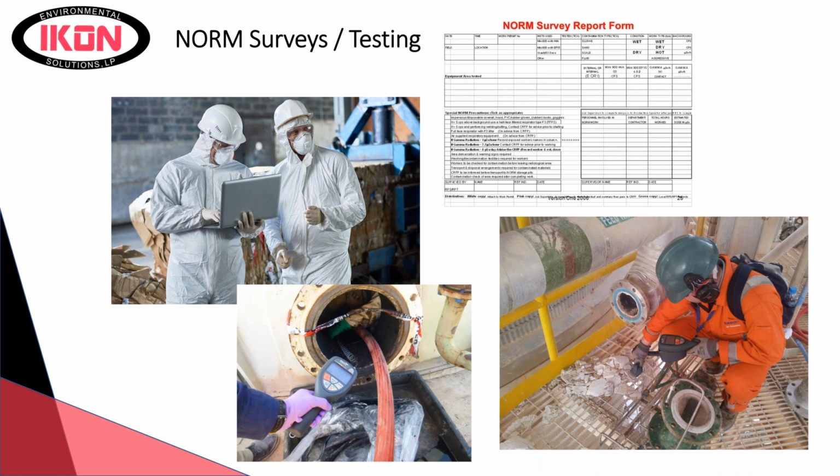Or, like I said, if it's a pile of pipeline rouge or a pigging line on a propane feed or some Y-grade field gas that pushed out a 6-inch Tootsie Roll looking thing of sludge, you're going to use the gamma scintillation also, because some of the short-lived isotopes can give you pretty high exposure rates until they decay away over 10 to 12 hours. But then if you had high exposure rates, you're going to have a lot of surface activity and specific activity from the lead-210. So again, the 44-9 he was talking about, pancake Geiger counters, is pretty good.